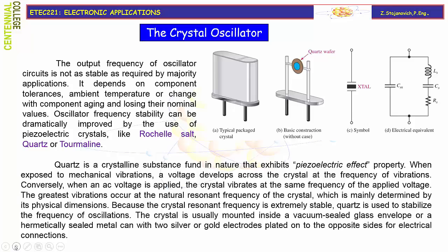The greatest vibration occurs at the natural resonant frequency of the crystal, which is mainly determined by its physical dimensions. Because the crystal resonant frequency is extremely stable, quartz is used to stabilize the frequency of oscillations. The crystal is usually mounted inside a vacuum-sealed glass envelope or hermetically sealed metal can with two silver or gold electrodes plated on the opposite sides for electrical connections.